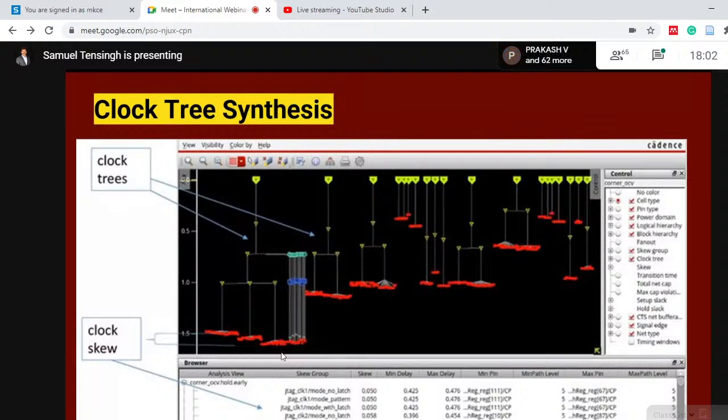If you have a balanced structure of clock tree, then it is easy for you to close timing. At the end of clock tree synthesis, you will report both setup and hold time, because in clock tree synthesis the clocks are propagated. You need to make sure your congestion is under control, and you need to analyze your hold time first to see whether you can fix it and what the major issues in hold time are. You may have to tweak the latency of certain clocks in the clock tree spec. So you need to analyze your clock tree synthesis.